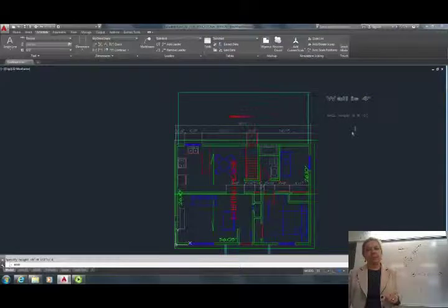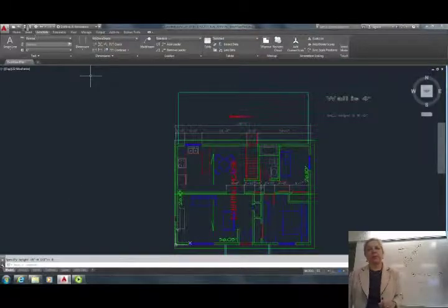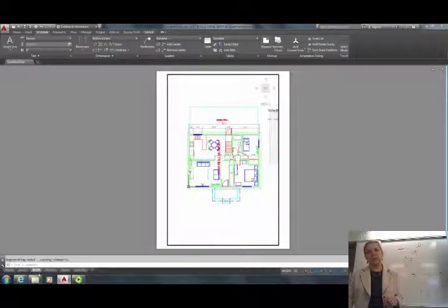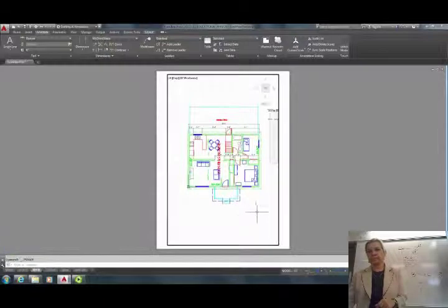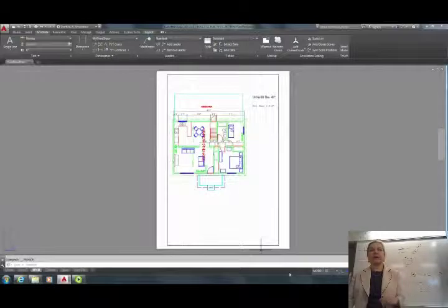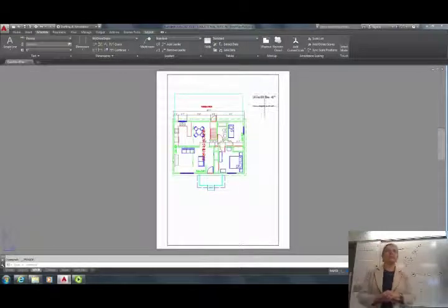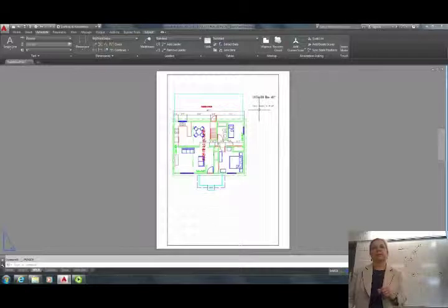But now if you go to your main layout tab, so let's save this. If I go to the main layout tab, and now in paper space, I'm going to click to paper space, and I want a 1/16 inch note. I'm going to come here just to move it, and then come to paper space, and I want exactly the same height, exactly the same font, but now I'm in paper space, and I want to do a general note, under my, let's say, revisions, and I want to use the same height, 1/16 of an inch on my small sheet.